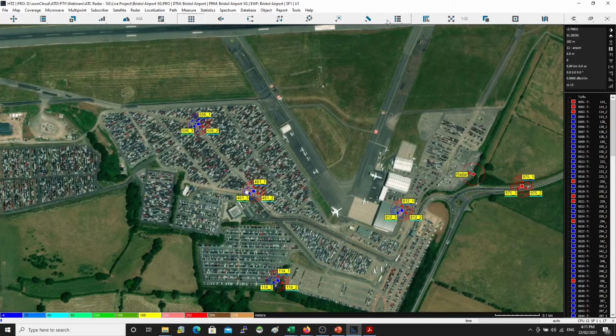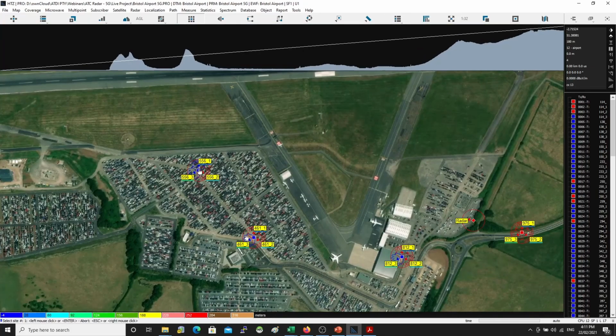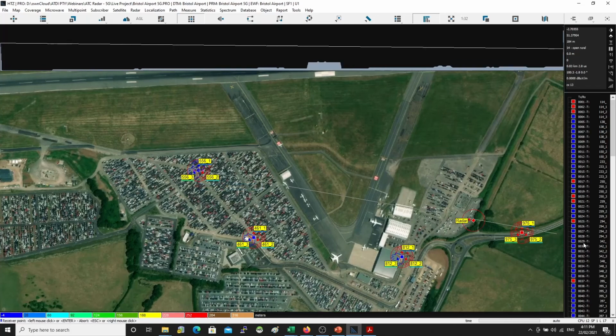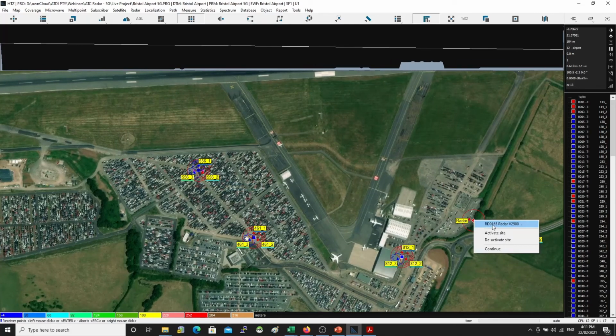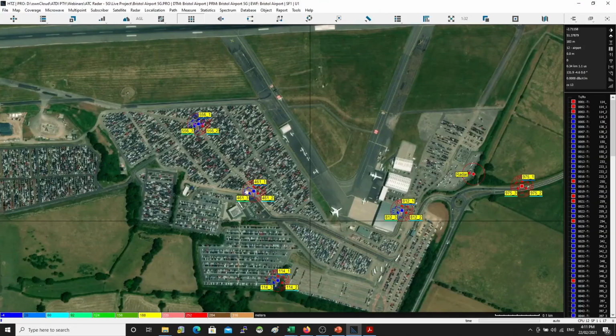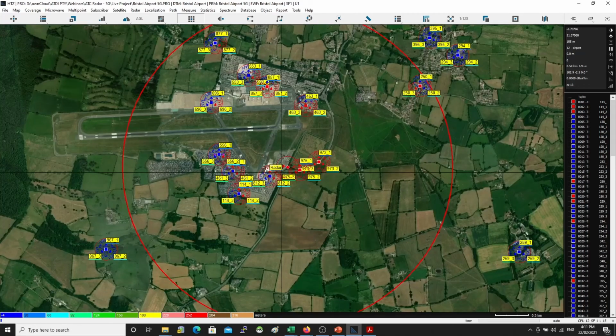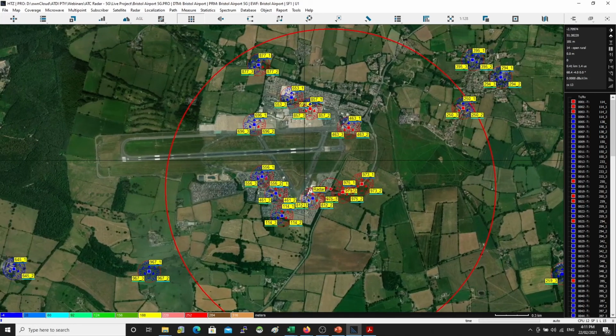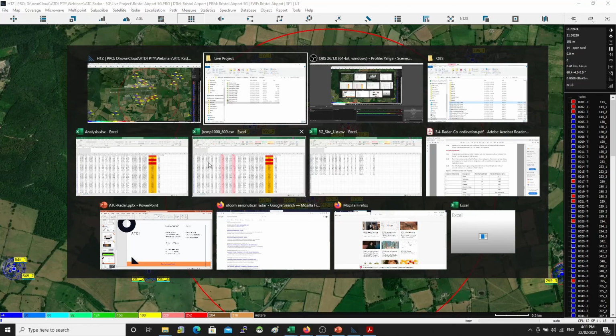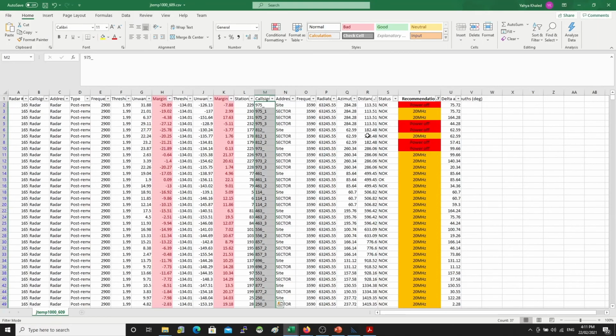Okay. Now if you want to do some quick analysis, see what's happening, you could do that. You could run analysis from here to the radar, and then you can see. Now, regardless, because these sites are within 1.5 kilometers, the software is using free space formula plus 6 dB margin on top of it in order to compensate for multipath and for reflections. So you see, we successfully now produced this comprehensive report. This report is extremely important to understand which site failed.